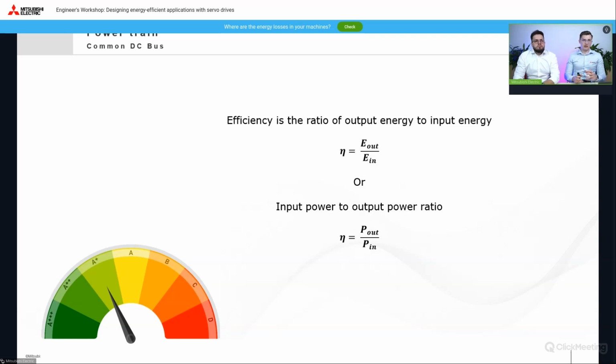And a great example is the incandescent lamps, so older light bulbs. They were popular around, I don't know, 10, maybe 15 years ago. In many cases, they can no longer be found in shops because they have been displaced by LED lamps. I think they're even illegal right now. And why? Because in the case of incandescent lamps, only 5 to 15% of the electrical energy supplied is changed into light. So the other part, this 80% more, is changed into heat. And of course, from the lamps we need to get light, not the heat.